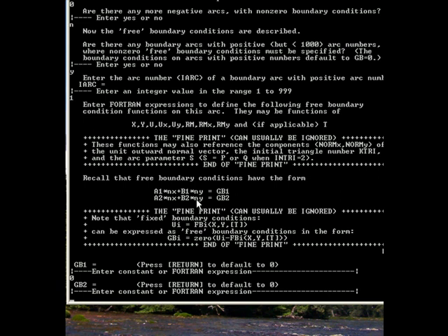Well, basically you can just say 1 times 10 to the 20th power times u equals 0, and that's essentially u equals 0, because it doesn't matter what the left hand side is. The right hand side is 10 to the 20th times u. That essentially makes u equal 0, and that'll work just fine. But actually PDE2D allows you to just simply write 0 of u, which is going to be exactly the same. See here, so that's how you can mix boundary conditions. If this tells you that the normal derivative is 0, this tells you that u is 0.